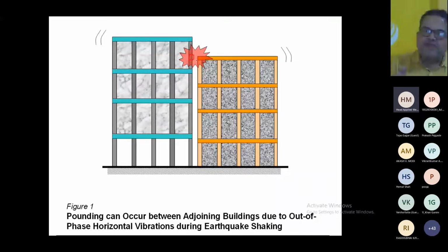Now, if we have designed both the structures correctly from an earthquake point of view, even then if this slab hits the column, we have not designed this column for this impact force, and your structure may fail because of this impact, right? If the column fails, it may lead to the collapse of the whole structure. Remember, this is very important, right?